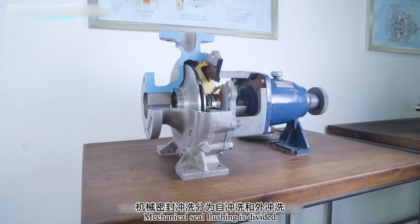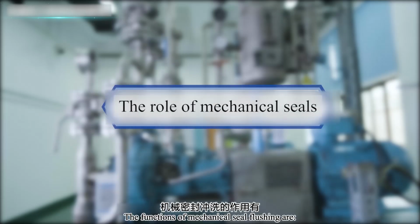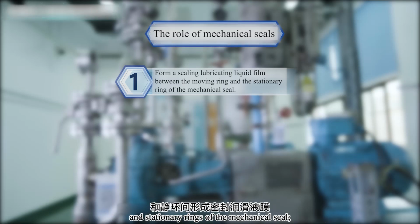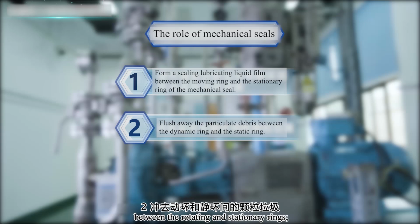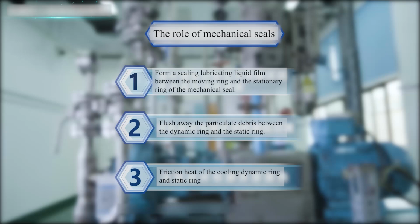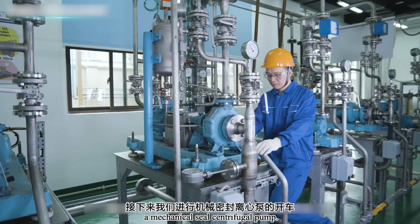Mechanical seal flushing is divided into self-flushing and external flushing. The functions of mechanical seal flushing are: first, to form a sealing, lubricating liquid film between the rotating and stationary rings of the mechanical seal. Second, to flush away particles and debris between the rotating and stationary rings. Third, to cool the friction heat generated between the rotating and stationary rings. Next, we will perform the start-up of a mechanical seal centrifugal pump.